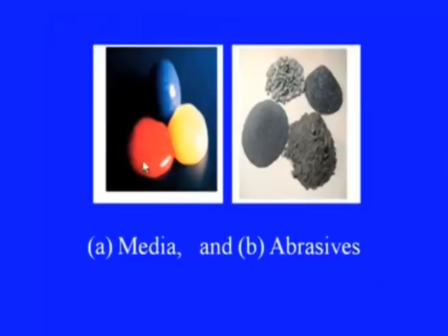Here are some of the carriers, and these are some of the abrasives used in this process. They are mixed together uniformly and that forms the working media. The tooling or fixture in this has the primary function to hold the workpiece in proper position between the two opposite cylinders, in the path of the media.